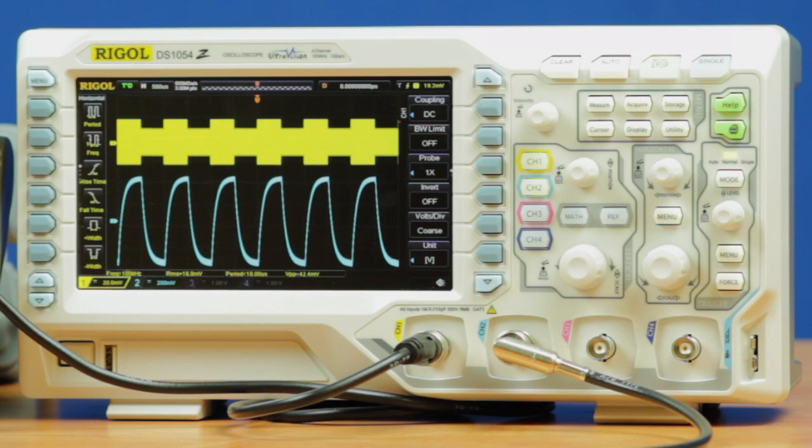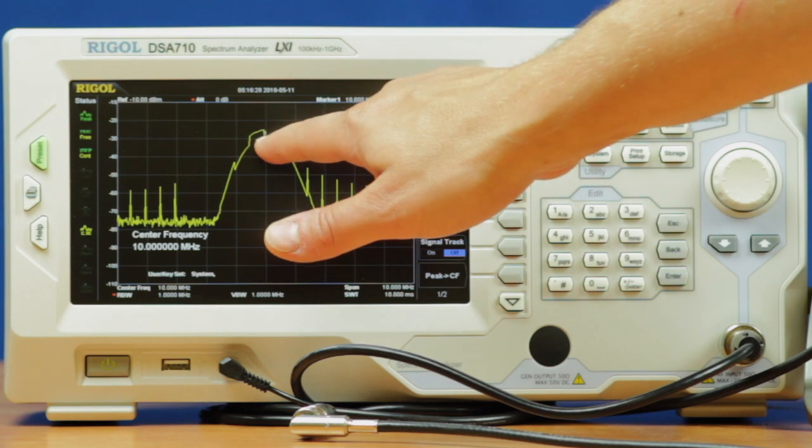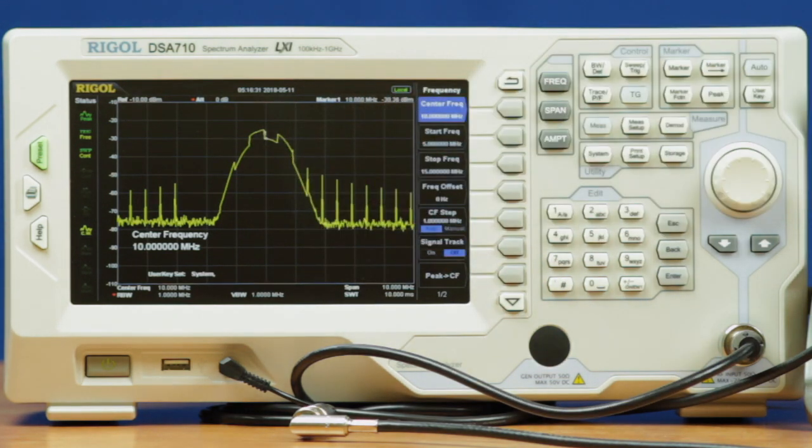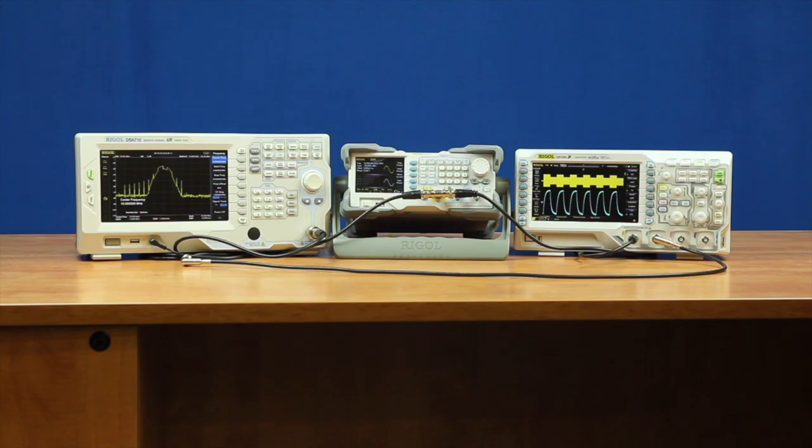If we looked closely at the spectrum analyzer, we can see the amplitude modulation changes here as they go from periods of high and low within a single sweep. So that creates a little bit of spectral energy, but really is a great way to see both the time and frequency domain view of an amplitude modulated digital signal, in this case an amplitude shift key.